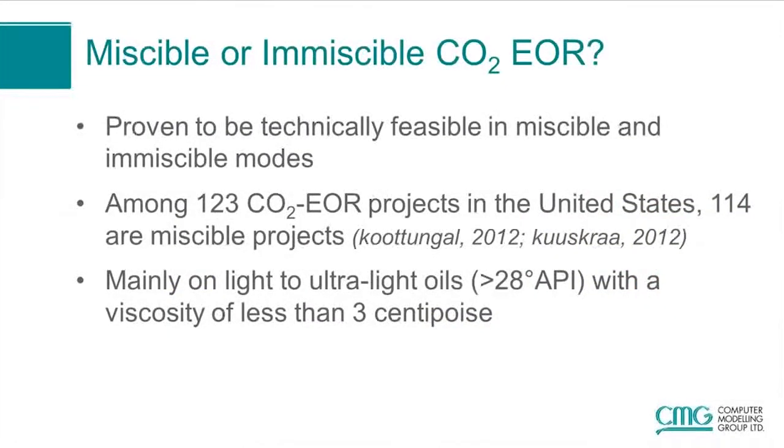Carbon dioxide EOR can be in miscible or immiscible modes, and it has been proven to be technically feasible in both modes. The carbon dioxide EOR miscible process is preferred because it has higher recovery compared to the immiscible mode. Because of that, among 123 carbon dioxide EOR projects in the US, about 114 are miscible processes. Even the non-miscible carbon dioxide EOR process is still attractive because of the oil viscosity reduction and the oil swelling by the dissolution of the carbon dioxide.